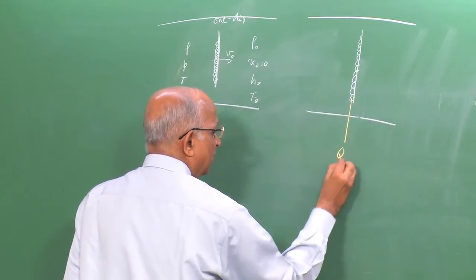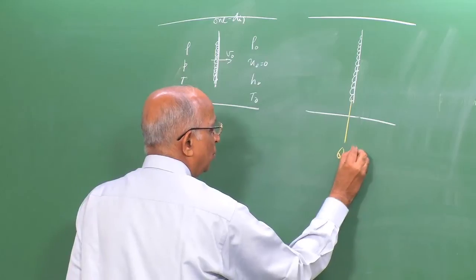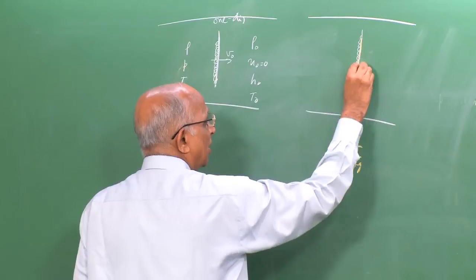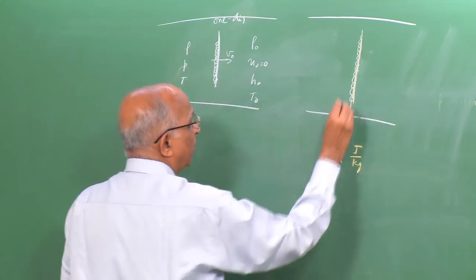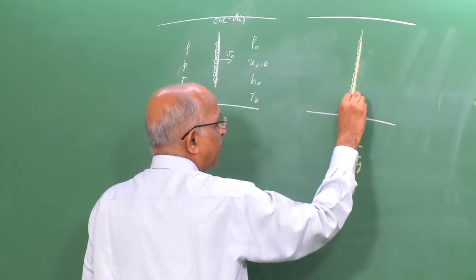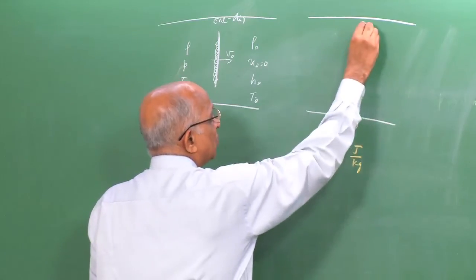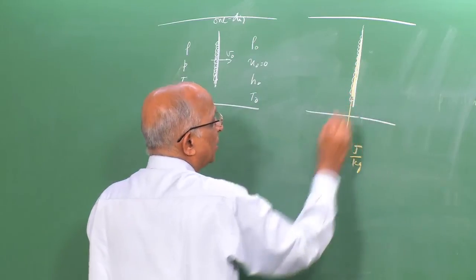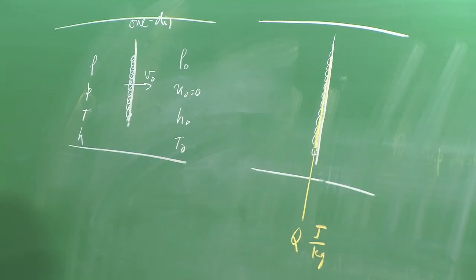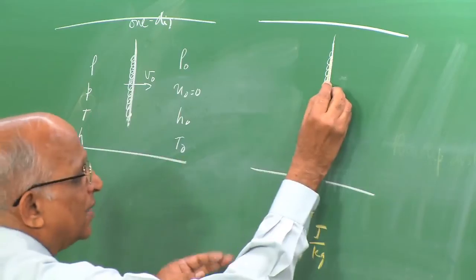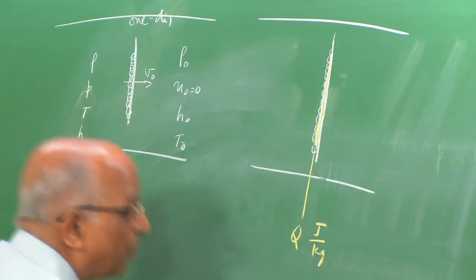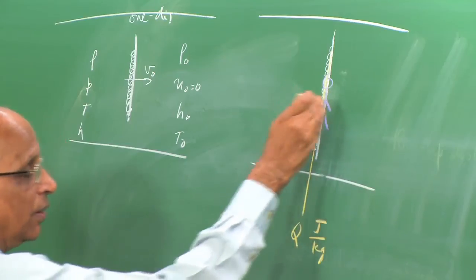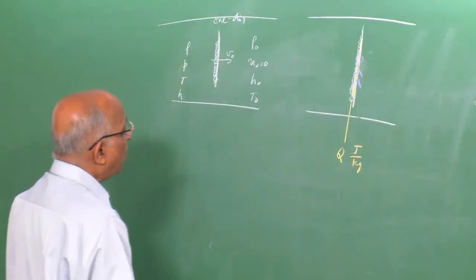Let us say that the heat release in chemical reaction is equal to q joules per kilogram. This is the energy which is released in the chemical reactions here at the shock itself. That is, behind the shock, chemical reactions are happening, and I am still considering a one dimensional picture. I have the shock front, and behind the shock front I have the chemical reactions. Now, instead of this moving, I sit on the wave, that means my frame of reference is with respect to the front over here.